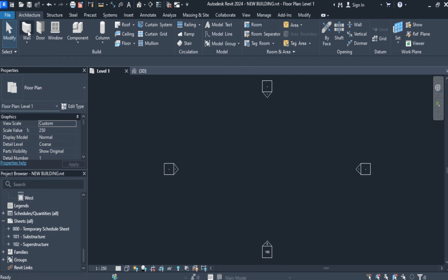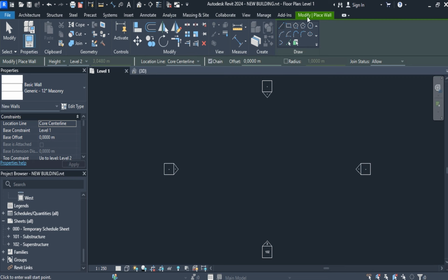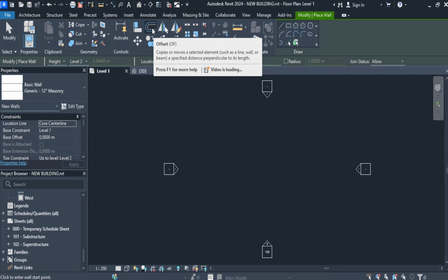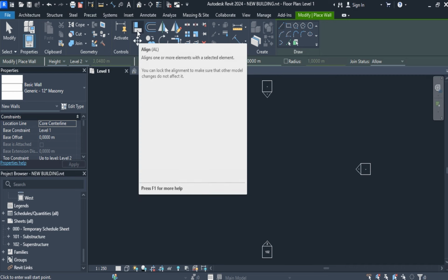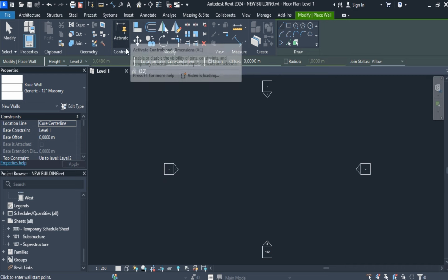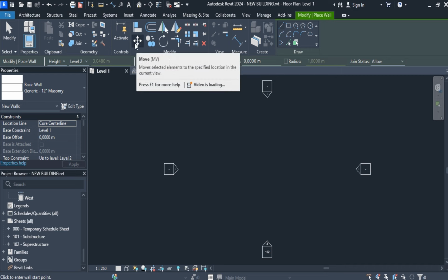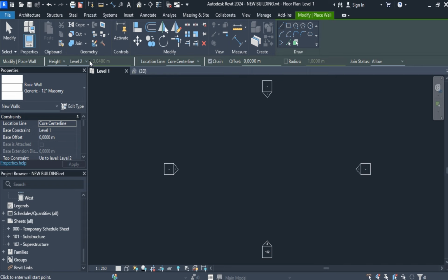So when you select an element in Revit, the Modify tab appears, and on this Modify tab, it has icons which you can use in drawing, creating, modifying, or populating the element into the project. And these modification icons, the copies, the offsets, and the moving, help you to work faster. Instead of creating an element twice, you can copy it or move it. That means save time.